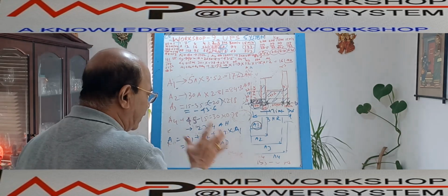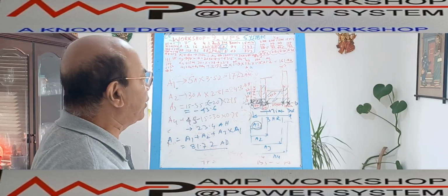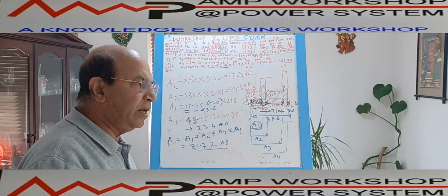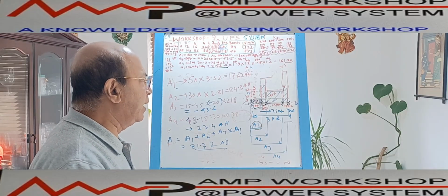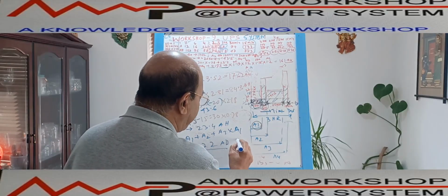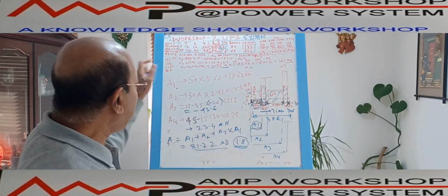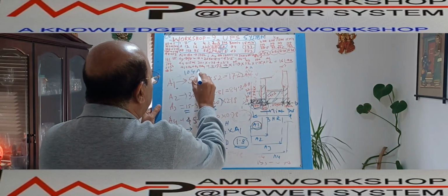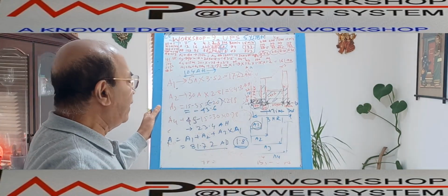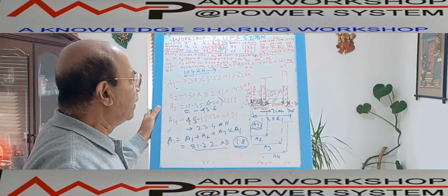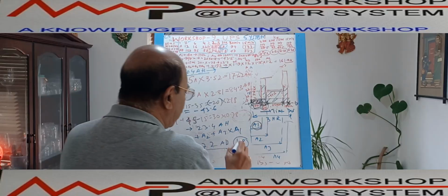Now this is the uncorrected capacity. We are considering this battery is operating at an ambient temperature of 10 degrees centigrade in a cold country. That is the first consideration. Second consideration, we are thinking this battery will be discharged up to 1.8 volt. After that, we will not allow the battery to discharge, because the capacity of 104 ampere hour which we are stating is when the battery is discharged over 8 hours and the battery voltage will be 0 after discharge. But here we are considering the battery will not be allowed to discharge up to 0 voltage.